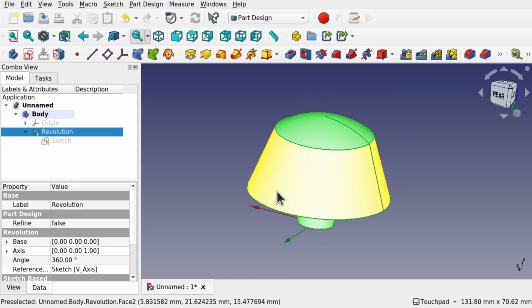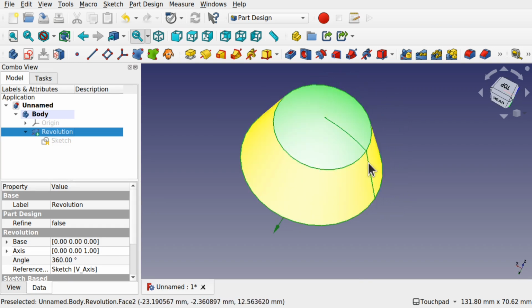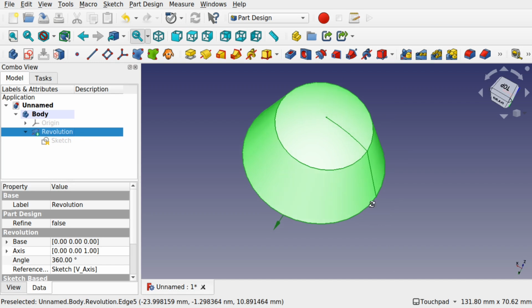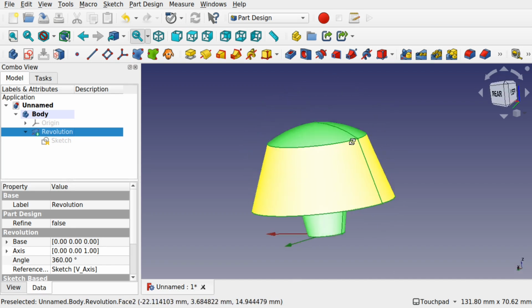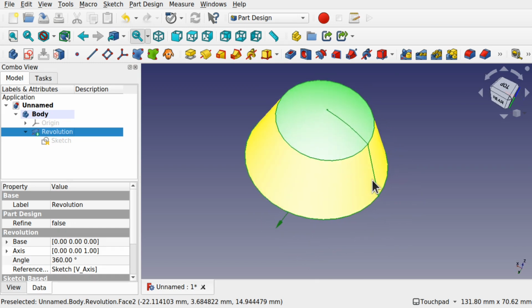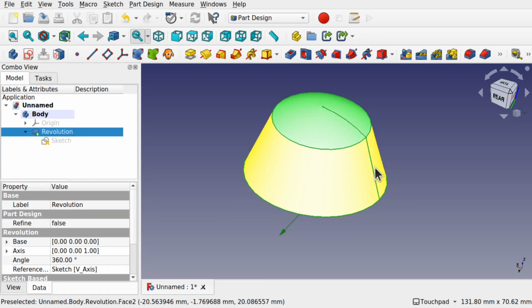Now if you look at control knobs, what you'll notice is that we're able to orientate the object, because we would have some kind of ridge that runs along here showing where the top part is. So this would be on 0 on the cooker, so we can rotate this around. That's really easy to do with this because we can utilize one of the operations that we were talking about earlier called a sweep. Sweep needs a path and a profile. Let me just show you how a sweep works in a new document.